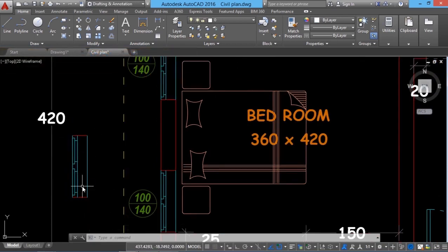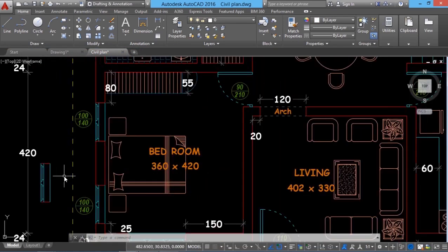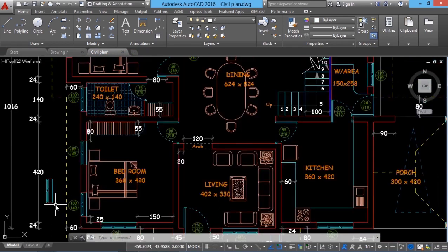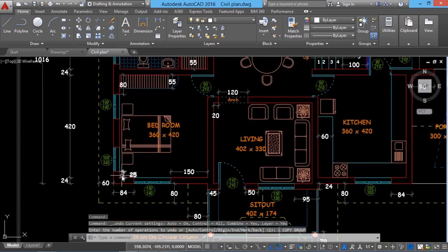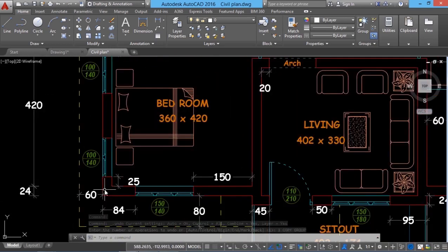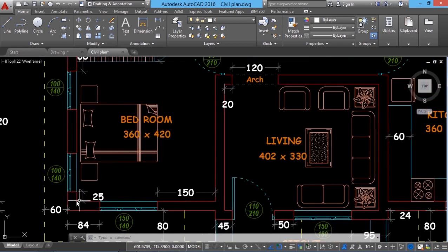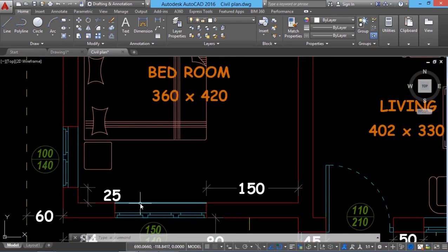That means in a situation when you want to make several copies of the same window, you will end up creating more objects, which will increase the file size as well as regeneration time when you work. This is where you actually need to make use of blocks. In addition to handling repeatability, AUTOCAD blocks give a tremendous advantage in editing. We will cover all these details in this tutorial.